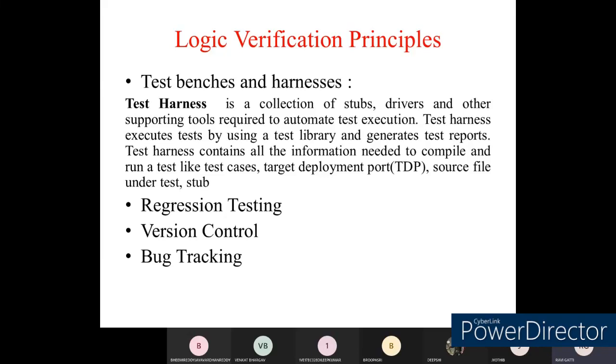Verifications we are going to do. So there are varieties of levels for the testing of the silicon wafers. We call it testing of a chip, and that can be offered at different levels. The first level we call the wafer level, the second level the packed chip level, the third level the board level, the next level the system level, and the last level the field level.